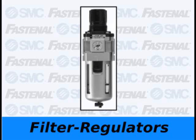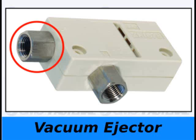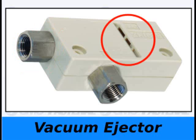Like every process, it starts with an air filter regulator to keep the air clean and to set the perfect pressure. Don't forget to recommend an OSHA lockout valve. This thing is called an ejector, and it turns air pressure into a vacuum suction. Air pressure comes in here and exhausts out here. I know it looks like a big whistle, but I promise it's nice and quiet.